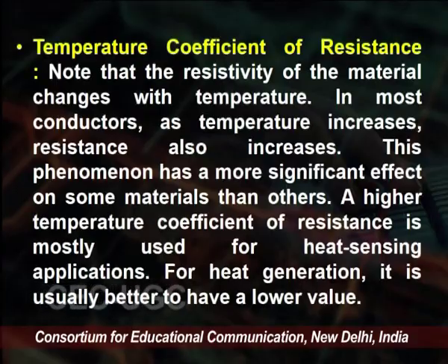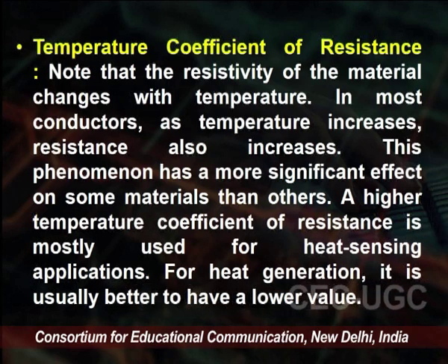Another important point is the temperature coefficient of resistance. As we use resistance as a heating element, the resistivity of the material changes with temperature, and in most conductors, as the temperature increases, resistance also increases. This phenomenon has a more significant effect on some materials than others.